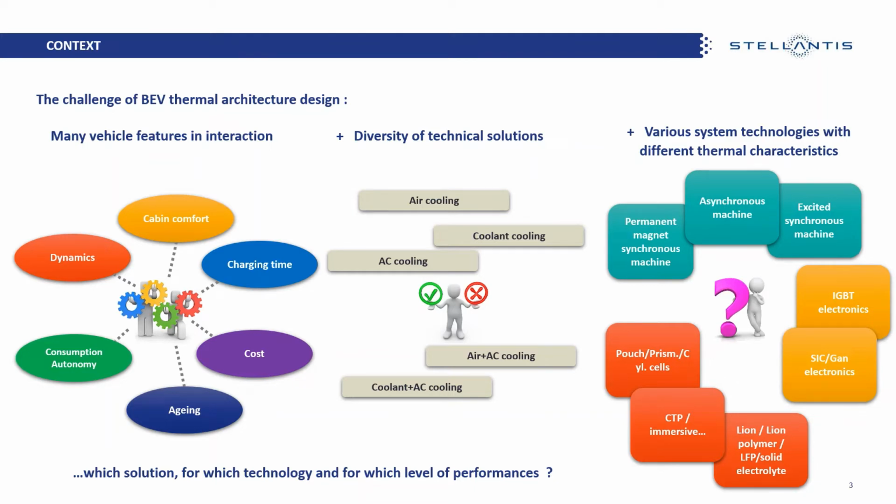And there are various technologies and thermal input, synchronous, asynchronous machines, IGBT versus silicon carbide technology for inverters, and so on. So the challenge is to do the right choice for the best performances, the lowest cost, and to do this in a short period of time, for instance, in the early step of the project.